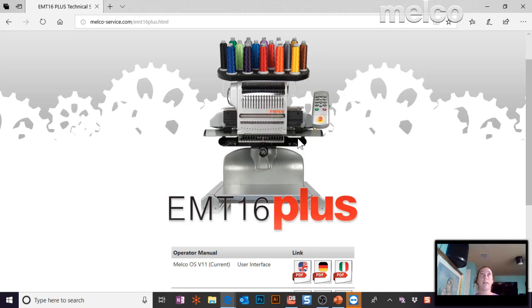There's another red exclamation point that'll tell you to make sure you take off any clamping system. Because again, that's another reason your needles can fall, if you leave a clamp on the machine and it hits the back of the needle case, it shoves the head off, so then all your needles fall. So those are really the two. Make sure these covers are always on, always back on before you leave the machine. Don't power it off and then power it back on with these covers off.